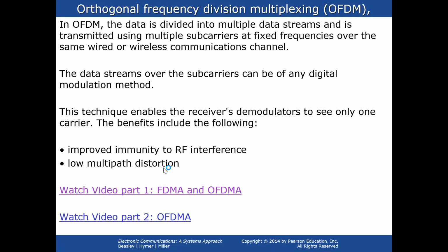As these subcarriers are modulated with data, they gain bandwidth centered around the subcarrier's frequencies. Guard bands are used to separate them in the frequency domain. We can represent this transmitted signal in the equation form as shown here, where the summation of individual symbols multiplied with different carrier frequencies is transmitted at radio frequencies.